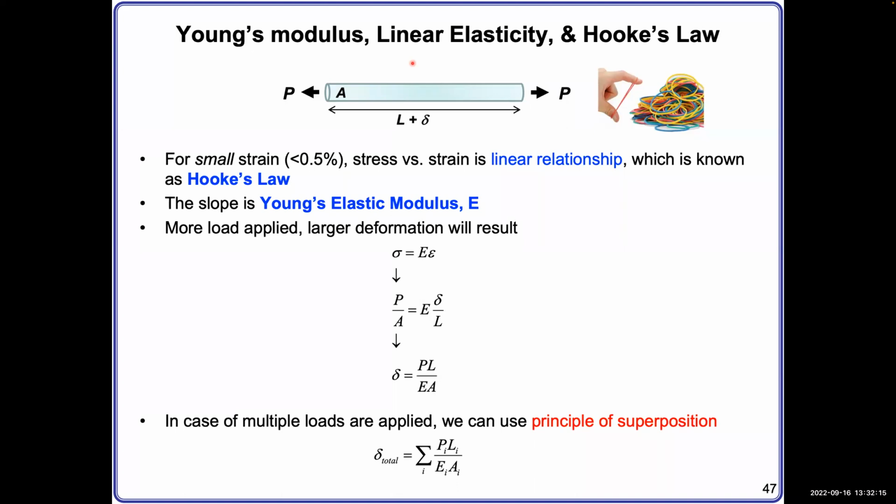But the beam we are going to discuss in the future sections is different. It's not that thin. For the beam, the cross-section area and the length are sometimes comparable, very similar. So the beam can sustain not only axial force, but also off-axial force. That means you can apply force perpendicular to the beam, and that causes a moment, a torque to the beam. That is also fine for the beam. Okay, so step by step, let's first learn what a bar is.